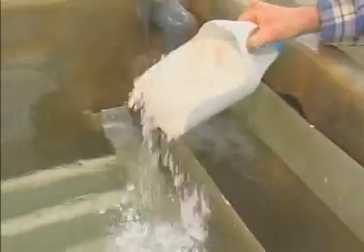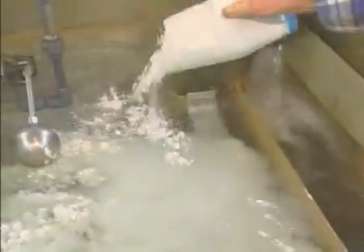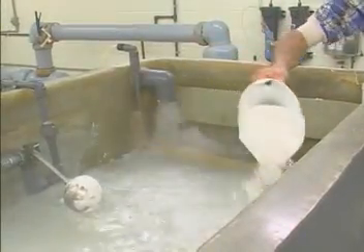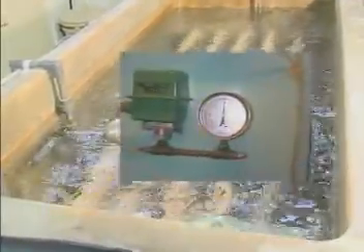To start a filter run, DE is added to water. Enough DE is added to evenly coat the entire surface area of the plenums. This is referred to as the pre-coat. As the water is drawn or forced through the filters, the particulate matter is trapped in the pore spaces of the DE. As the available pore spaces are closed off with the particles, the head loss begins to increase.